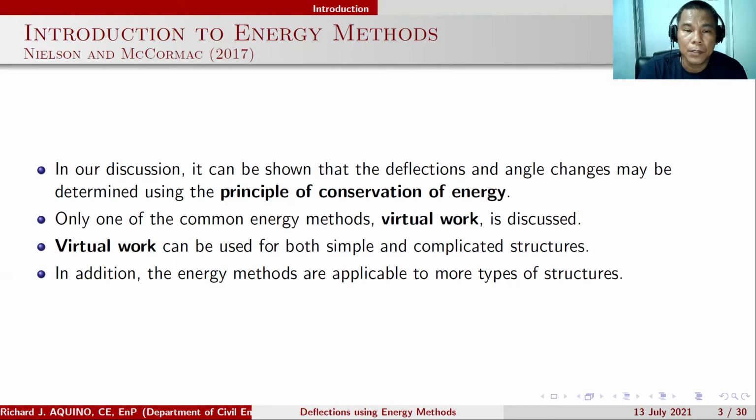In our discussion, it can be shown that the deflections and angle changes may be determined using the principle of conservation of energy. Only one of the common energy methods, that is the virtual work, will be discussed. Virtual work can be used for both simple and complicated structures. In addition, the energy methods are applicable to more types of structures.